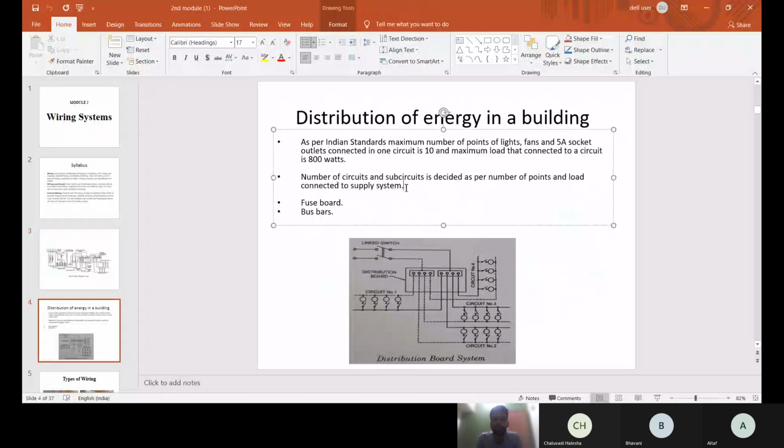You can observe here that the distribution board which I have shown is connected through the fuses, and fuses should always be connected with the phase, followed by the switches. The neutral wire should be connected to the lamps and fans, which is looped there, and it should not be linked to the switches. The actual connection to the switch comes from the lamps and fans.